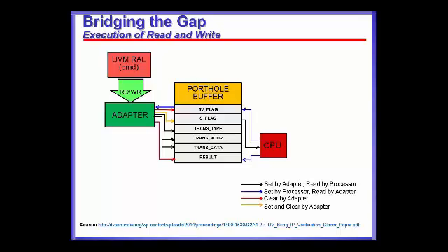And then to expedite the process, what we can do is write an ASM. So that's what we have done. We have written an ASM code where we are actually using CPU registers directly to expedite the process of fetching that instruction from the memory buffer.